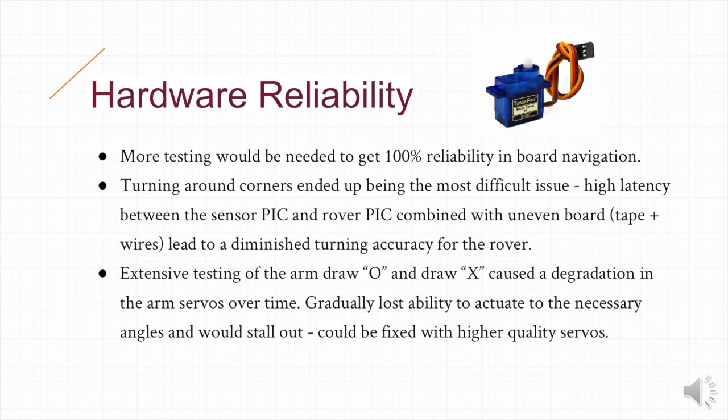From a hardware perspective, significantly more testing would be needed to get to 100% reliability in board navigation. The major issue which we encountered was in turning around corners. The combination of high latency between the sensor PIC and the rover PIC combined with the uneven board structure led to a diminished turning accuracy for the rover.